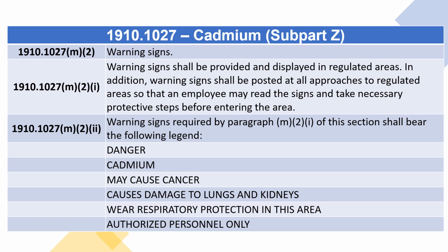1910.1027 M2 2. Warning signs required by paragraph M2 I of this section shall bear the following legend: Danger. Cadmium may cause cancer. Causes damage to lungs and kidneys. Wear respiratory protection in this area. Authorized personnel only.